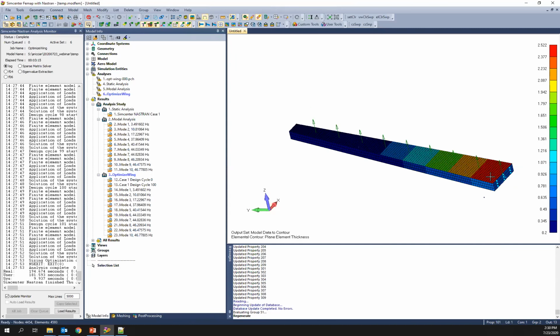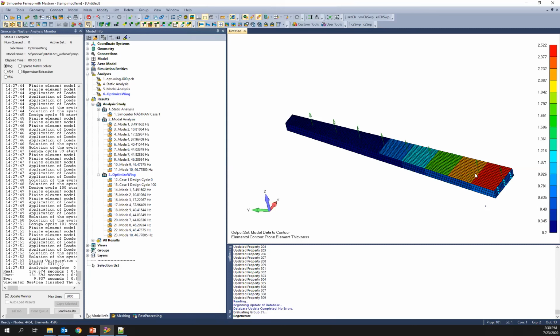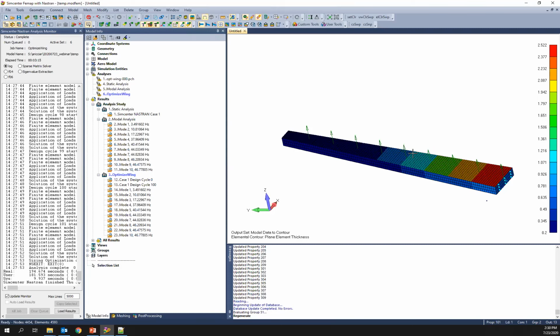So now we see this modified thickness where we have distributed, we see the taper that we expect for this type of wing. And so the optimizer has added material and has tapered the wing down to, this is the lower bound. So we didn't allow the optimizer to reduce the material beyond this, but we see, about from midspan, we have a tapered wing by this contour.